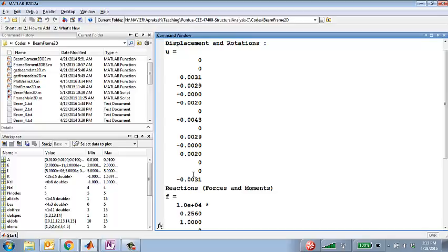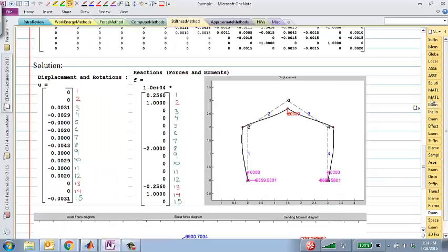Andrew? Multiply what by AE over L? Deflections at what points? For the axial components, that's right. But for this problem, for frame problems, getting the axial components is a little bit different from the beam problems. You remember what we did for the truss problems when you had to calculate internal forces? How did we do that? Yes, we do have to convert it to the element coordinates, and that's the transformation we need to find the axial components. So let me show you, maybe remind you first what we did for the truss parts, and then